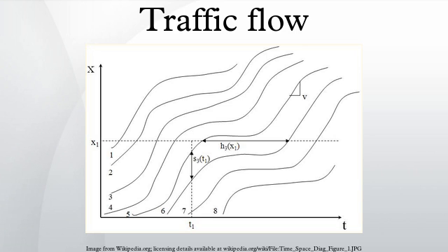Incommensurability of Kerner's three-phase traffic theory and classical traffic flow theories: the explanation of the traffic breakdown at a highway bottleneck by an F→S transition in a metastable free flow at the bottleneck is the basic assumption of Kerner's three-phase traffic theory. The three-phase traffic theory is consistent with a set of fundamental empirical features of the traffic breakdown. None of the earlier traffic flow theories incorporates an F→S transition in a metastable free flow at the bottleneck. Therefore, as mentioned above, none of the classical traffic flow theories is consistent with the set of empirical features of real traffic breakdown at a highway bottleneck.